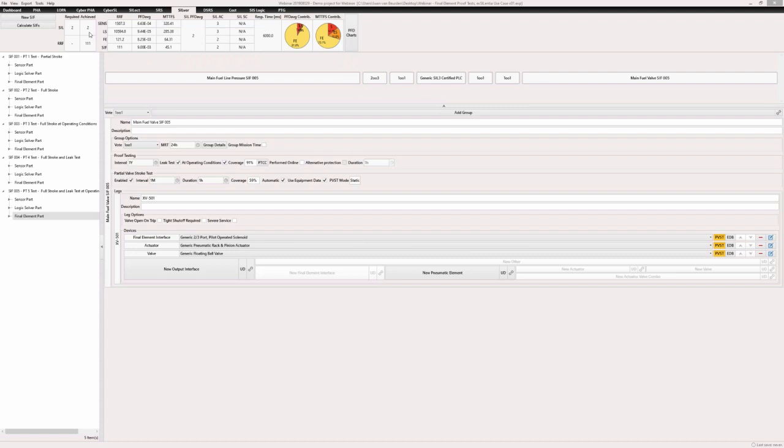So I cannot answer your question, do we always need to do partial stroking for SIL 2, with a yes or no. It really depends on the equipment that you're using. You could even assume that you replace the valve once a year, and thereby have 100% proof test coverage. Now that's probably not going to happen, but you could make that assumption. You could end up with a lower probability of failure. In this case, with this data, yes, you would need to do something extra to get a higher risk reduction. But it's not a rule that it always needs to be that way.